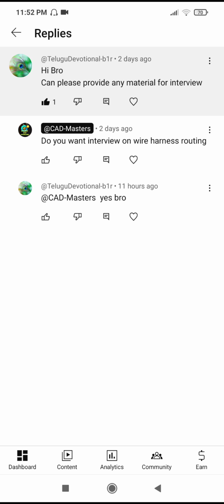After the schematic there is a part of 3D routing. 3D routing is also created in the Creo Parametric software. There the 3D visualization of the wires is created, actual 3D connectors are placed, packaging is done, and the 3D wire is routed. From that we will get how much length of wire is required, because it is 3D routed wire. After 3D routing we will get the length in flatten view. Okay, there is some process in the software. So finally one drawing is prepared in flatten view.